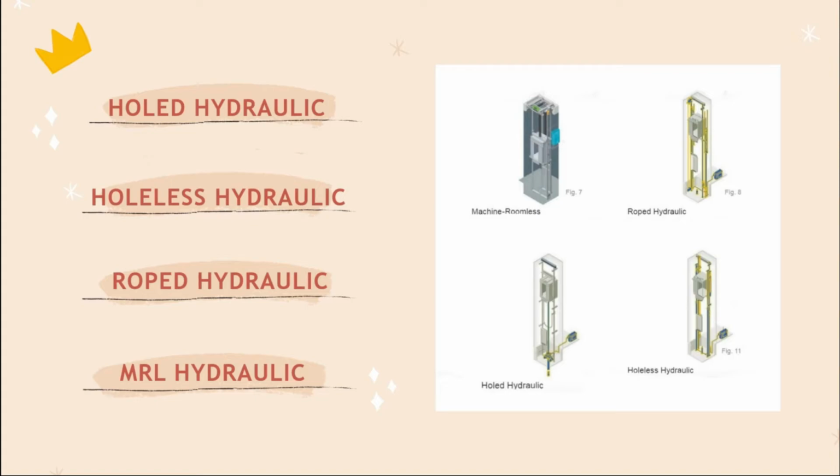Prior to the arrival of machine roomless elevators, height restrictions and sun shadow regulations, among other factors, meant that the actual building had to be considered, and hydraulic elevators were used when there were limitations such as not being able to load heavy equipment. Because of their high capacity and suitability for transporting heavy loads, these elevators are currently in use in factories and warehouses. However, due to their structure, they are almost always used in low-rise buildings.